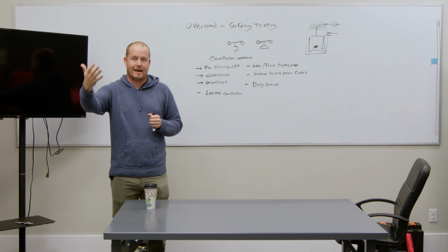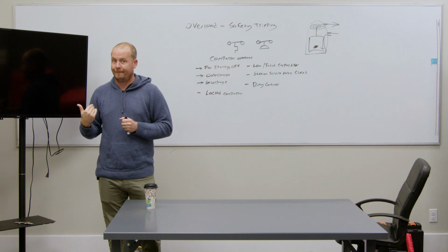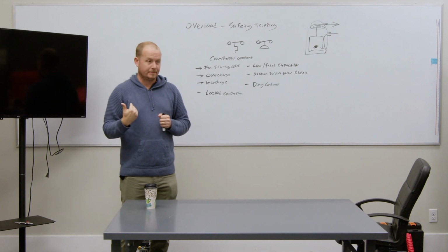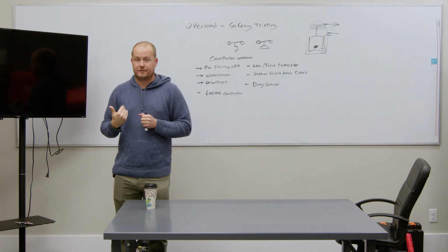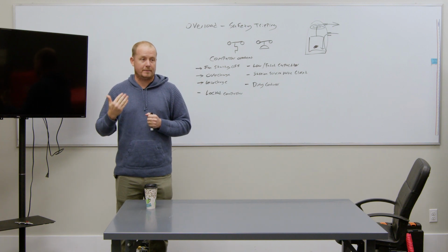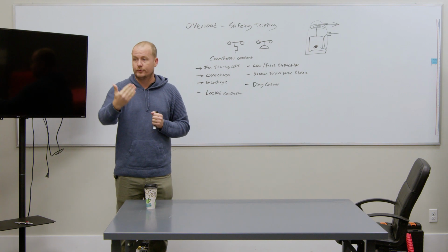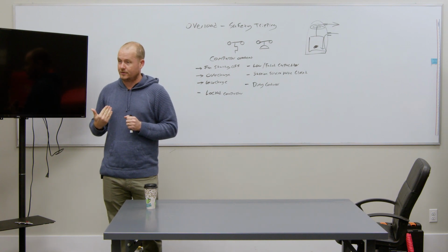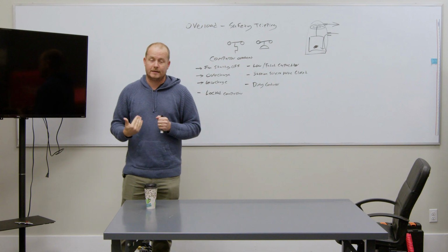It requires the refrigerant mass returning on what line? Suction line, right? So your suction pressure matters as far as compressor temperature. If you have really low suction pressure, that means you have low mass flow rate.